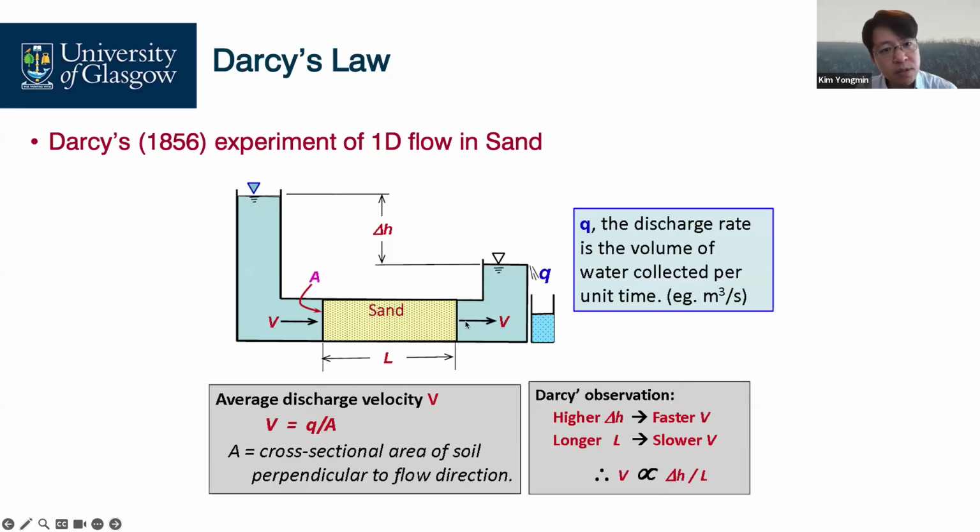What about point B? This point is exposed to air through this channel, not through the sand. So for point B, the pressure head would be the height from here to here.